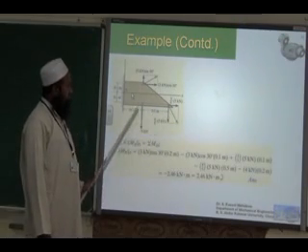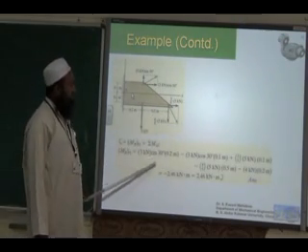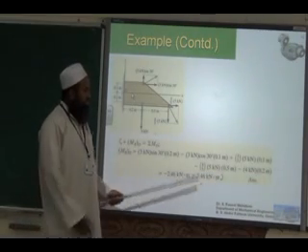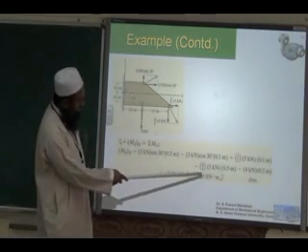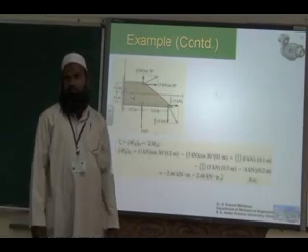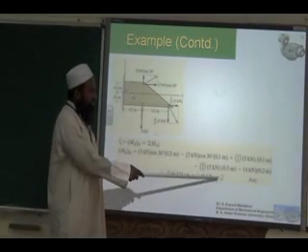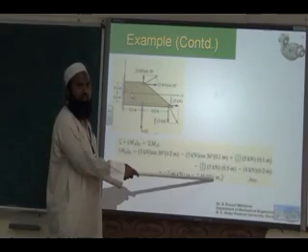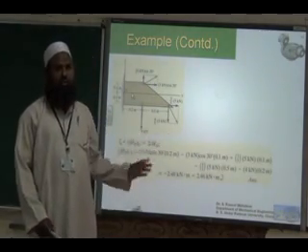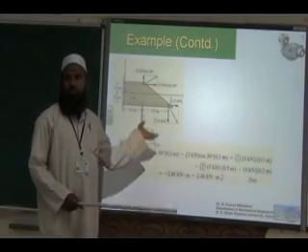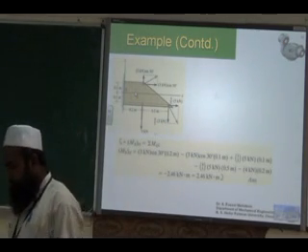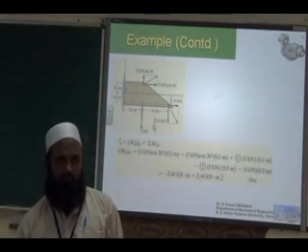Similarly, here we have the equation for the resultant moment. The resultant moment will be 2.46 kilonewton meter. Is it positive or negative? It's negative, so it will be clockwise. If the answer is negative, we say 2.46 kilonewton meter in the clockwise direction. So we transmit all the forces to point O. First we find the resultant force, then we find the resultant moment. Any doubt?